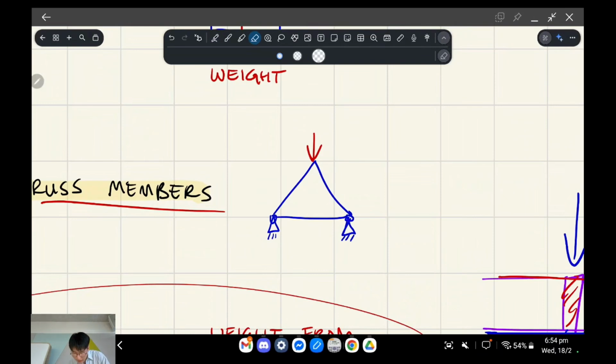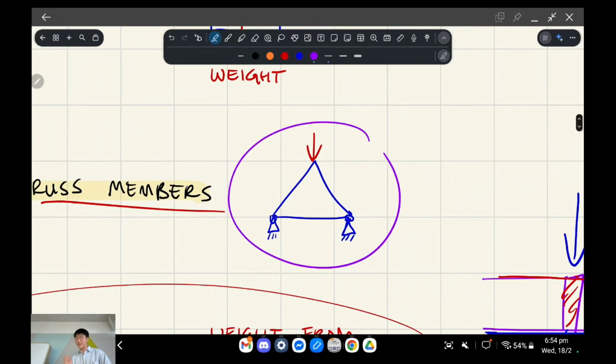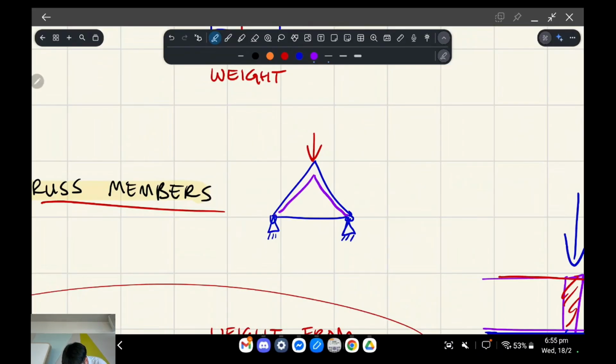Firstly, let's just say we have this triangular apparatus for a truss. It's got three truss members and it's simply supported, and we have a force coming down from the top. What we can do is draw its deformed shape. Essentially, it wants to sag down at the bottom, and it's getting squashed from that load at the top. So that bottom member ends up being in tension. I'm exaggerating the deformation significantly, by the way. And these two members are being compressed.